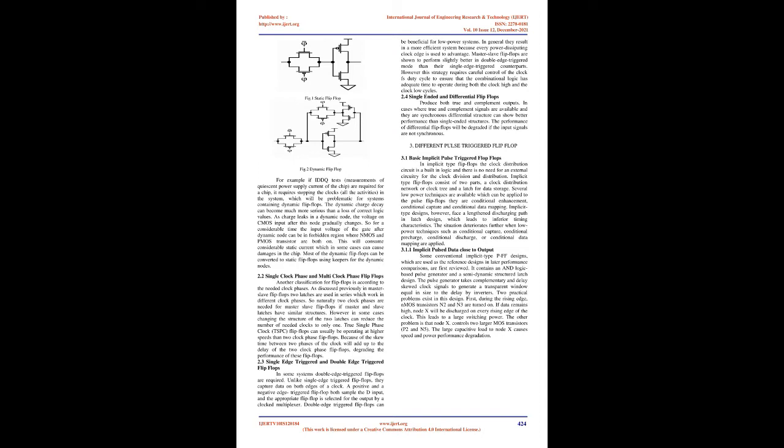Master-slave flip-flops are shown to perform slightly better in double-edge triggered mode than their single-edge triggered counterparts. However, this strategy requires careful control of the clock's duty cycle to ensure that the combinational logic has adequate time to operate during both the clock high and the clock low cycles. 2.4 Single-ended and differential flip-flops produce both true and complement outputs. In cases where true and complement signals are available and they are synchronous, differential structures can show better performance than single-ended structures. The performance of differential flip-flops will be degraded if the input signals are not synchronous.